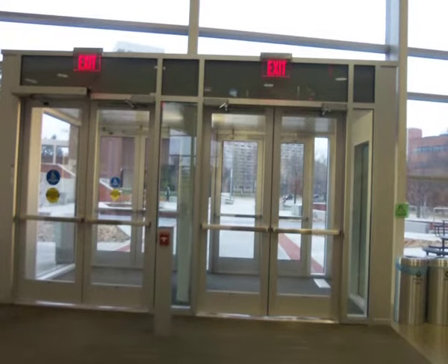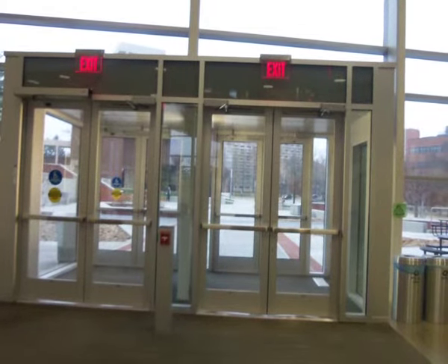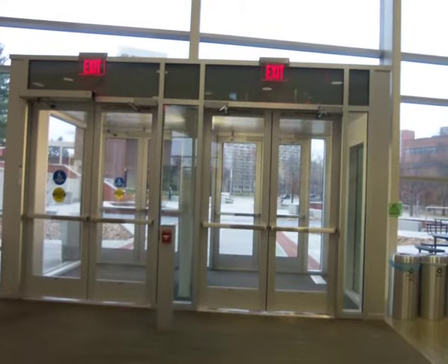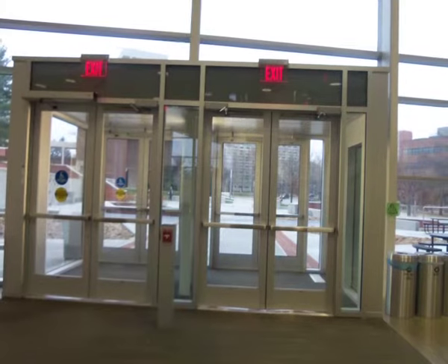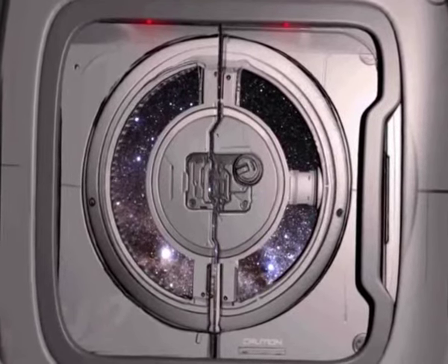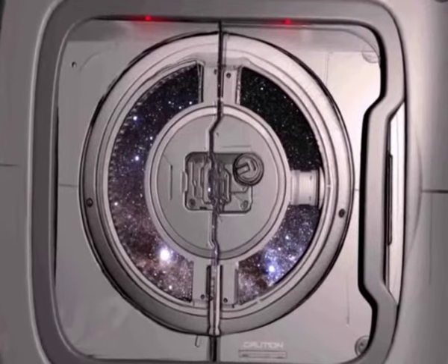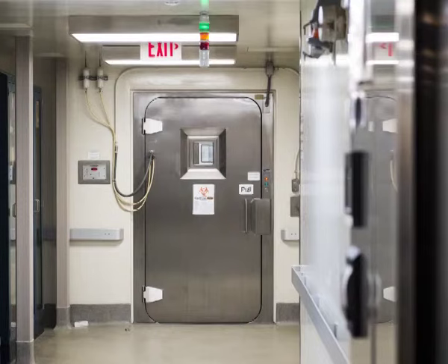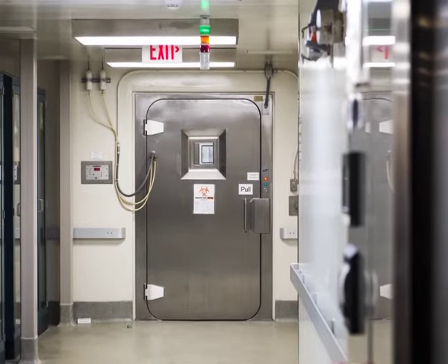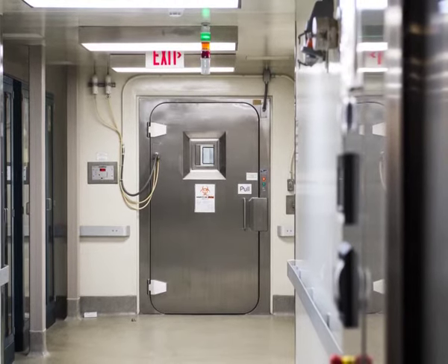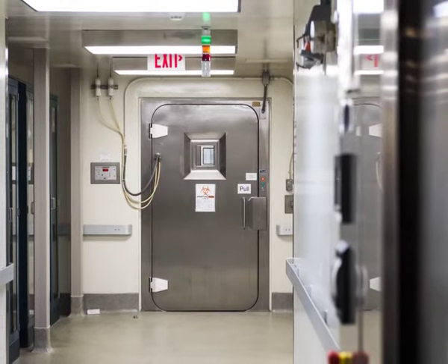Use of a double door or integrated sterilizer helps to ensure direct product flow, often from a lower to a higher classified area. Airlocks and interlocking doors will facilitate better control of the air balance throughout the aseptic processing facility. Airlocks should be installed between the aseptic manufacturing area entrance and the adjoining unclassified area.